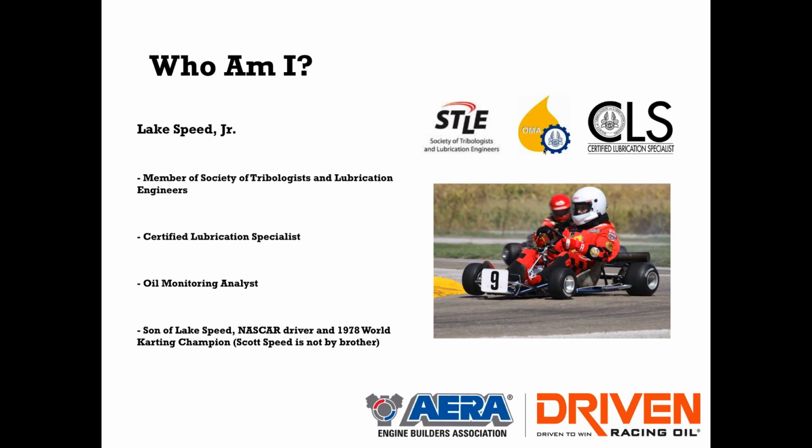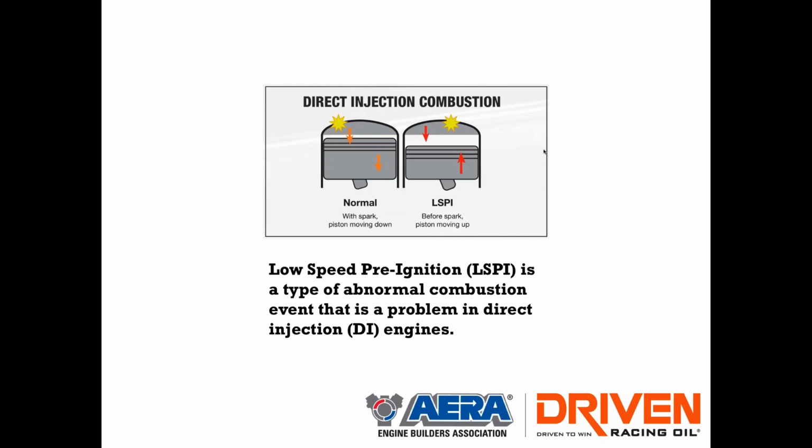But the interesting thing that's come up is this whole concept of low-speed pre-ignition, which is a detonation event. It's a little bit more unique than that. Obviously, the extremeness of the failure says it's not just a normal knock event. This is something way more than that. Obviously, you want to have spark initiate ignition. You don't want to have pre-spark ignition. They call it LSPI, low-speed pre-ignition, as this basic slide says.